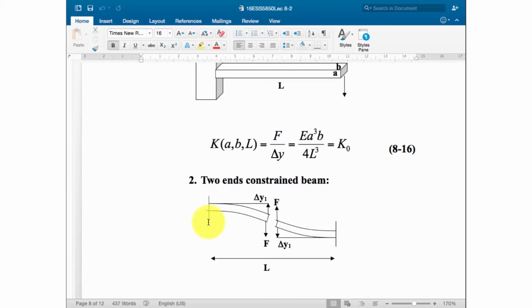So if you consider deformation like this, you cut from the center part. The center part is an inflection point. The inflection point means you change the slope from one slope to the other. Originally, you have a slope gradually increasing, then at the inflection point, the amount of slope starts to reduce. So the center part we call the inflection point.